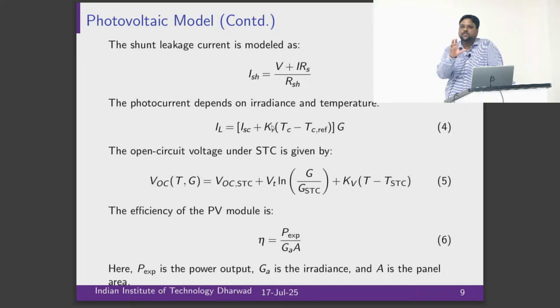Got it? So, basically we represent it as a current source. When you go for power electronics and do some kind of system level studies, we call this solar cell a current source. Okay. And mostly, if you remember, when you have a solar PV inverter, we classically model the controller as grid following, so that whatever the grid wants, you just inject that current.